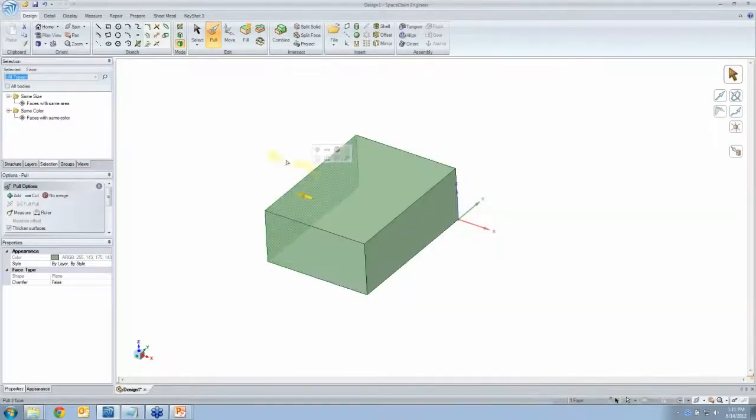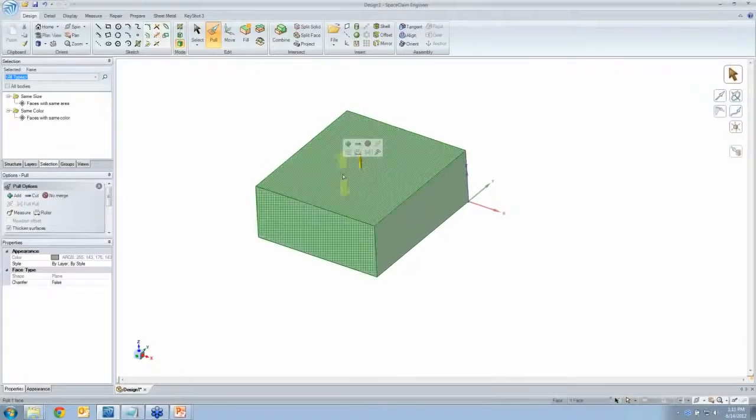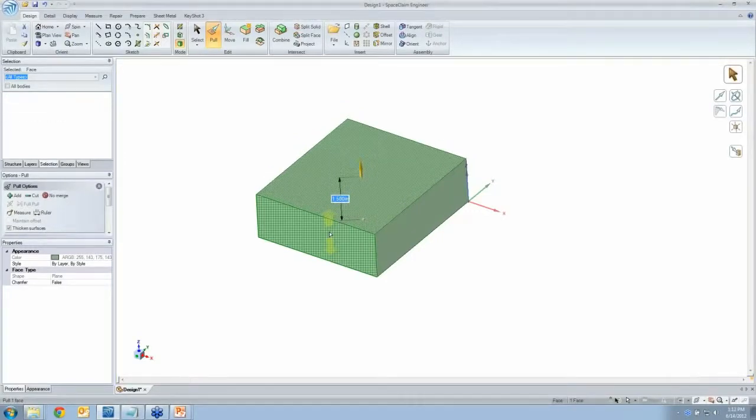Now, I've been pulling on this thing left and right, up and down. I have no idea how big it is. But at any time, I can put precision into the model wherever I want, just by putting something like a ruler dimension. So as I create the model at the beginning, as I'm going along, or at the end, I can always dictate geometry. I can dictate dimensions and say that needs to be 1.5 inches thick.